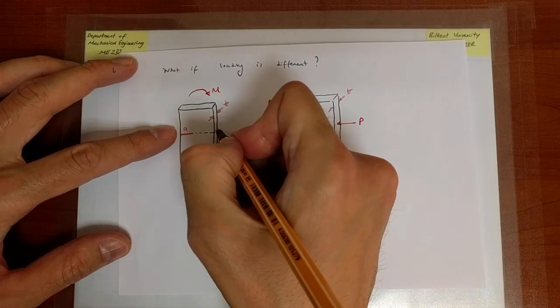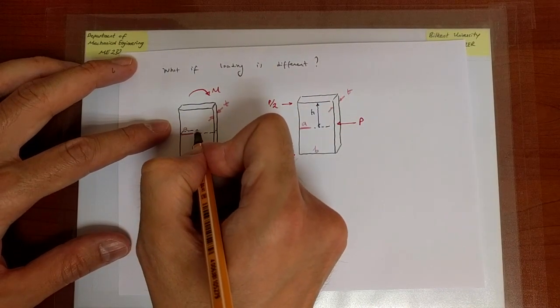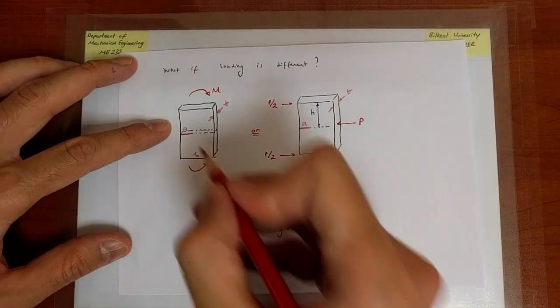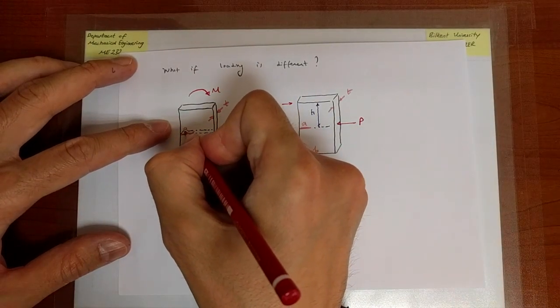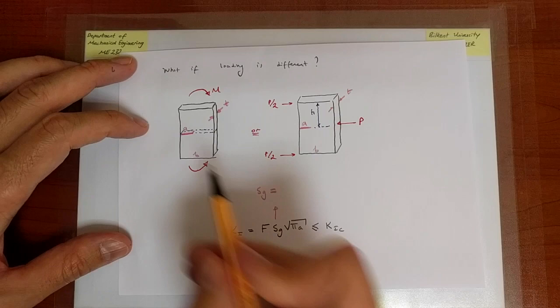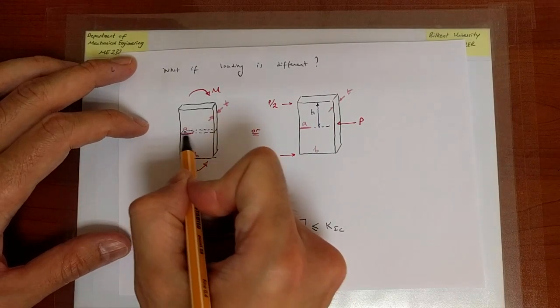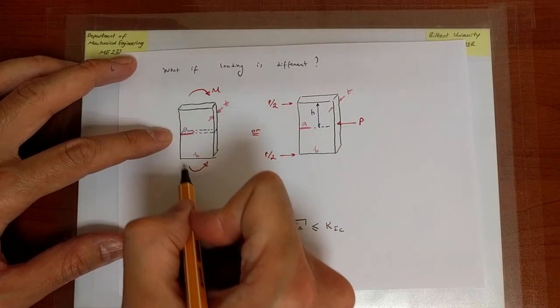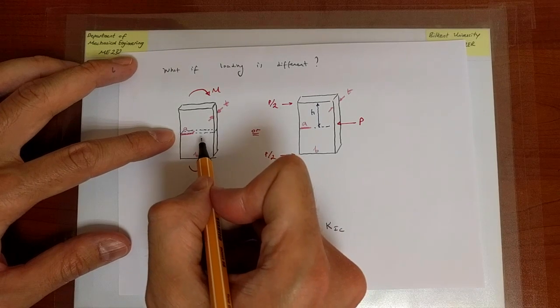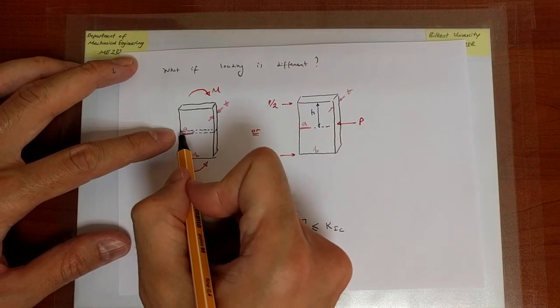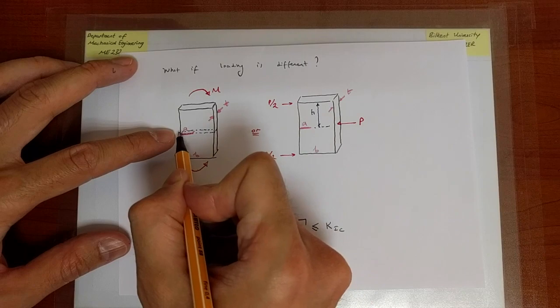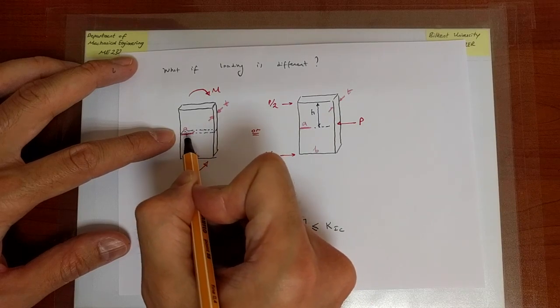Okay, so that cross section is like this, this portion of that cross section is actually a crack, but I omit its presence, so it's like this blue rectangle that I'm looking at. The plate is bent, and I would like to calculate the maximum stress at that cross section, but omitting the presence of the crack.